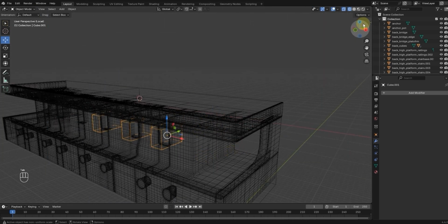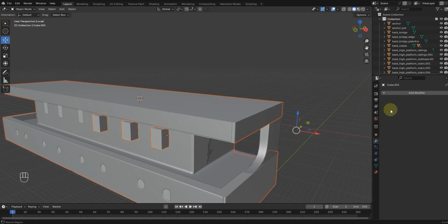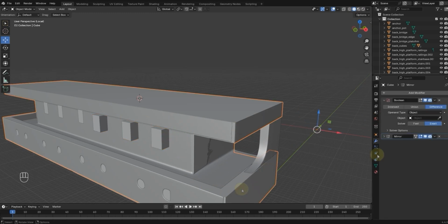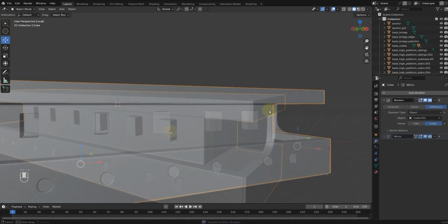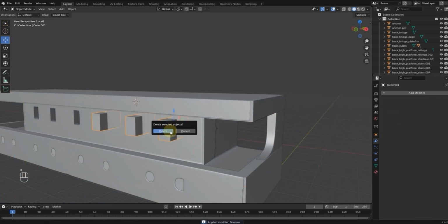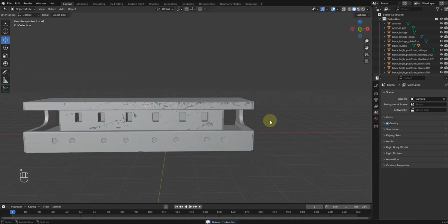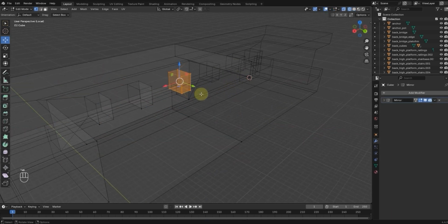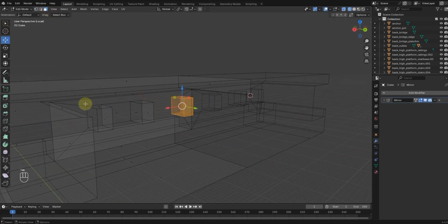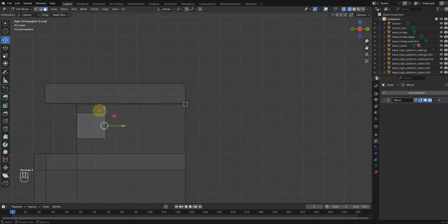Next thing I'll do is select the mesh and go into the Boolean modifier and select the cube again. And I guess if I apply this now, so if I delete the cube, the window space is provided, which is great. Fantastic. Now I'm going to delete the faces at the back of the windows. I'll probably go to the side, select all the faces and delete them.